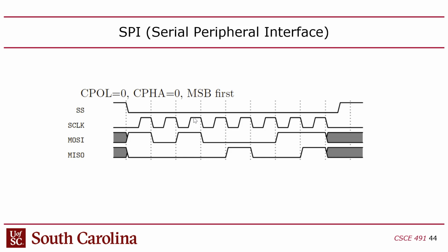So the slave select goes low and then goes back high because it's active low. If you count the number of cycles that slave select is low, in this case it's 8, because this is an exchange where 8 bits flow out from the master and 8 bits flow into the master, right? So there's 8 cycles in this case. It doesn't have to be 8 cycles, but generally it's going to be a multiple of 8 cycles whenever you do one of these, whenever you activate the bus. So this is a single exchange of 1 byte between the 2 sides of the channel, and thus its slave select is active for 8 cycles.